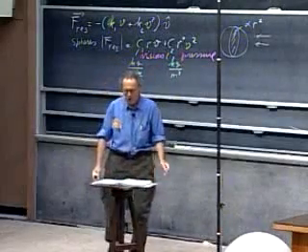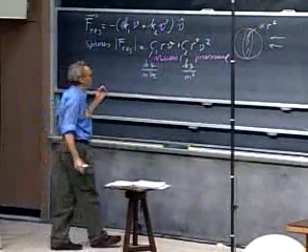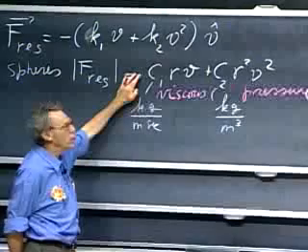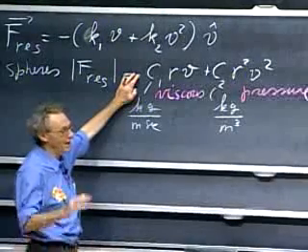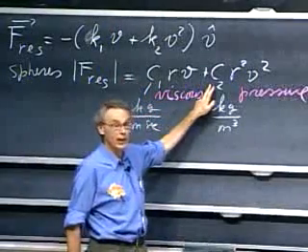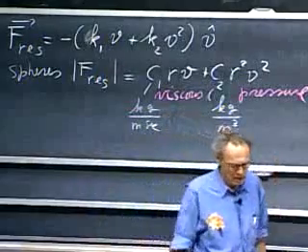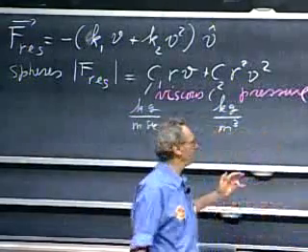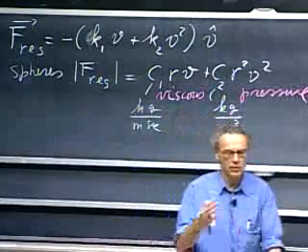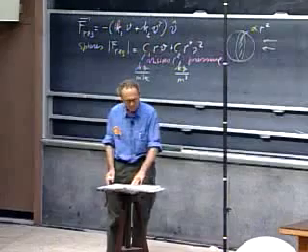Two liquids with the very same density could have very different values for C1. They could differ by 4 or 5 orders of magnitude. But if they have the same density, then C2 is very much the same. C2 is almost the density rho of the liquid. Not quite, but almost. But there is a very strong correlation between C2 and the density.